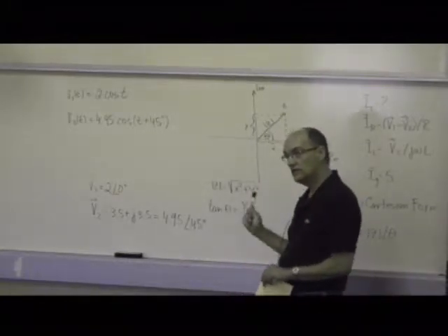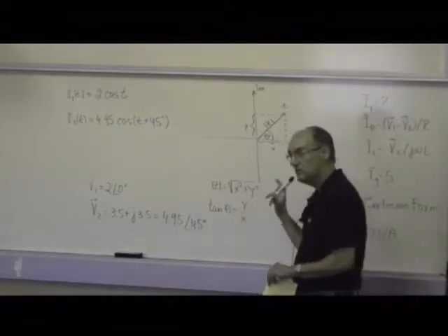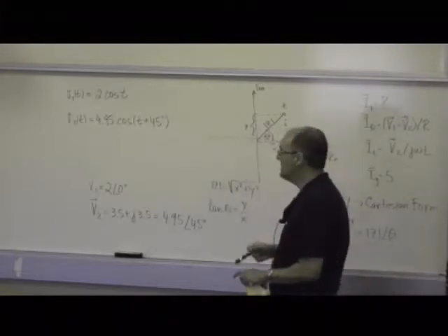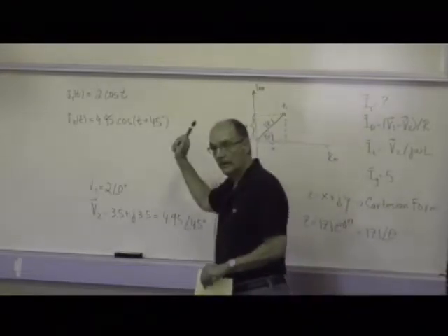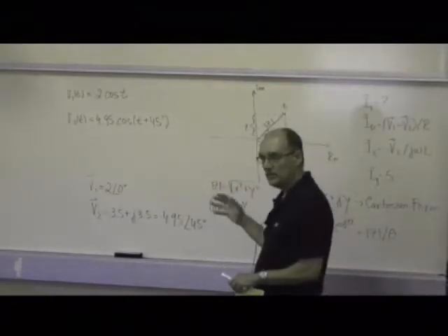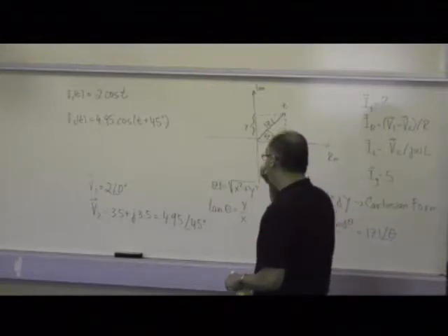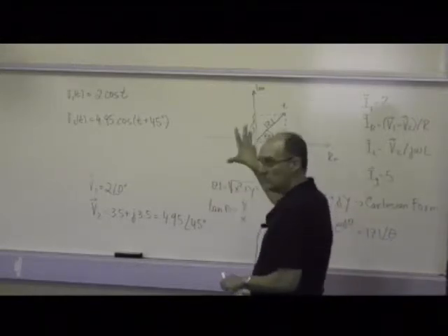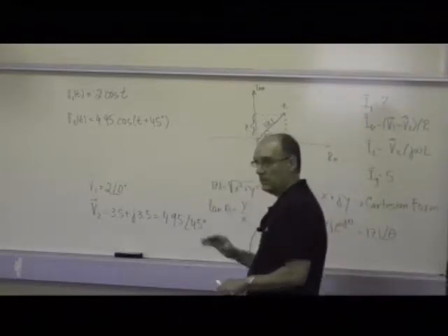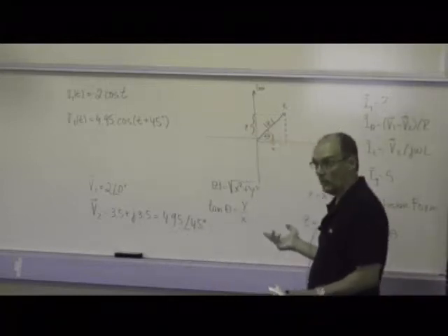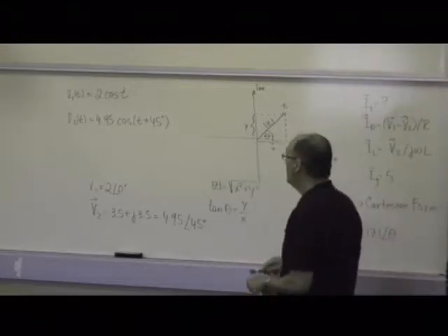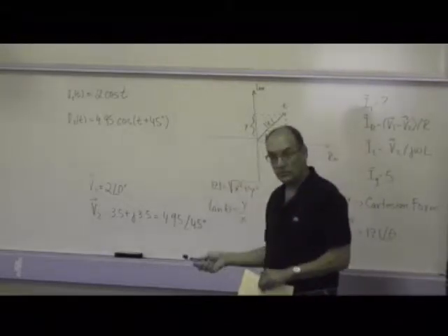But again, I emphasize the difference between the complete response and the steady-state response. Phasors don't tell you what happens in the transient period. They just tell you what you're going to end up with. With the transient, you'll need Laplace transforms, and we'll talk about that in the second half of this course, but not yet. So phasors are a powerful thing, but they don't give you the whole story. They give you the steady-state response, and that response is an important thing. That's how many circuits are designed to operate. That's how power systems are designed to operate. So it's not like it's not an interesting thing.